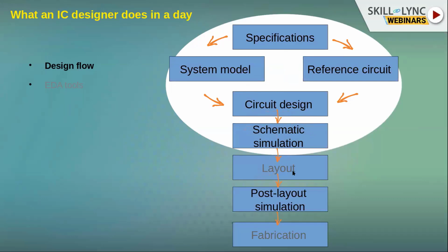Once it is laid out, for layout, in industry you will have a separate team who does the layout. Layout is where the physical way of realizing an IC comes in. You will be defining each of your transistors, resistors, capacitors, all the elements in terms of physical metal pieces, like how long, how wide, how close, how far.